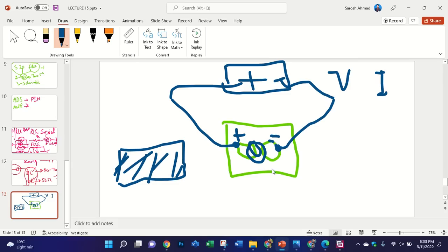But in the case where you don't have any full ground plane or partial ground plane on the substrate, like if you are using the CPW technique, then you need to create a very small stub, or a very small patch on the other side of the substrate, just to connect the shorting pin and to provide the ground for this negative point.